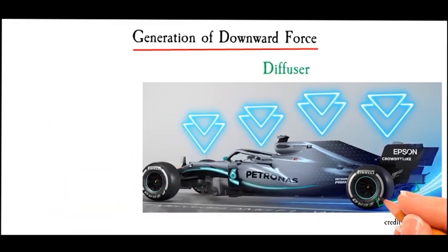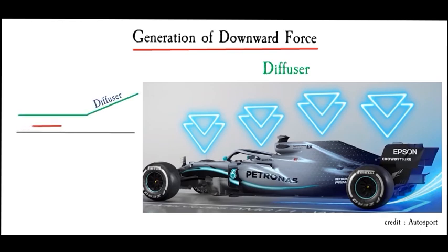The diffuser in the racing car further accelerates the flow of air under the car, helping to create a very low pressure region underneath, thereby increasing the downward force. This happens because the diffuser increases in volume along its length, creating a void that has to be filled by the air passing under the body. The Venturi effect accelerates the flow through the throat of the diffuser to create the desired low pressure.